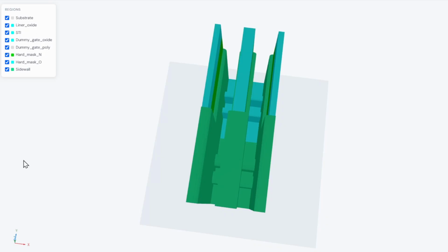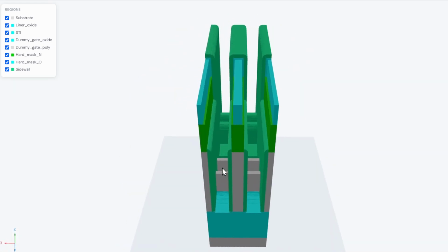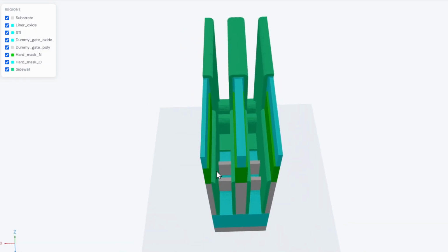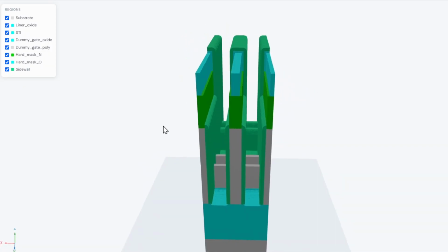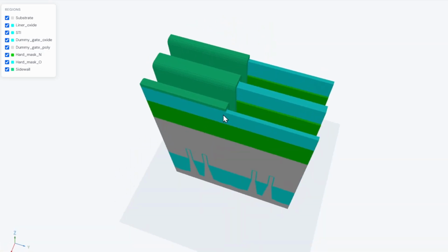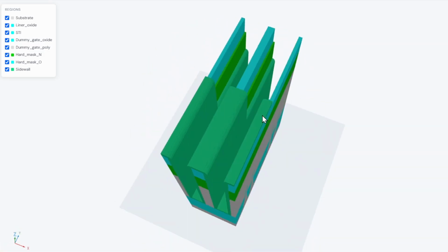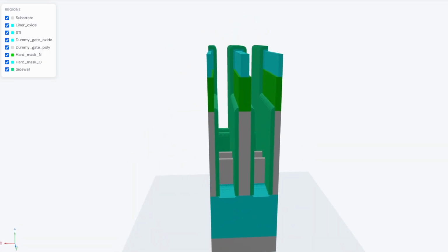By performing this etching process, now you can see that this silicon fin is revealed. Of course, the N MOSFET part is still covered by this silicon oxynitride spacer, so we have only the part for this P MOSFET.